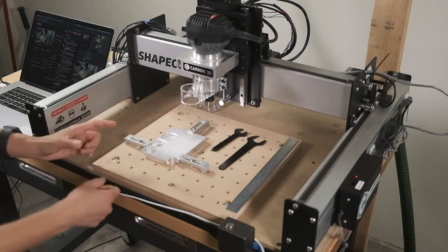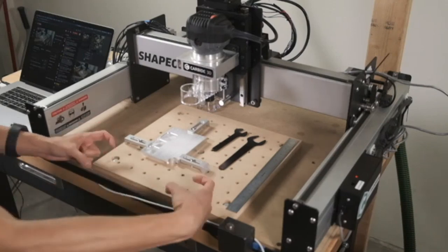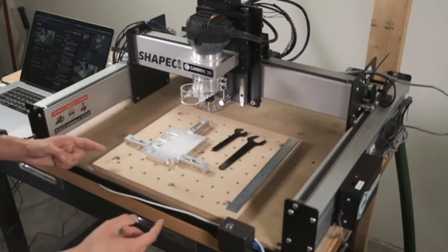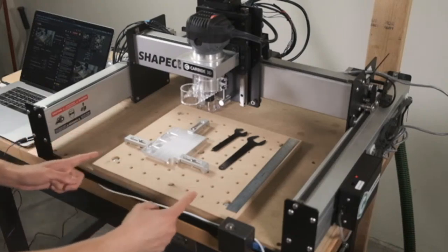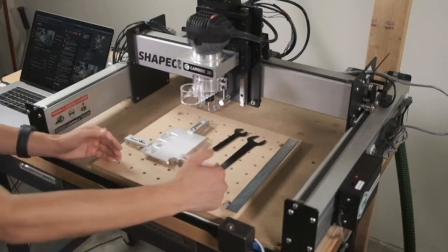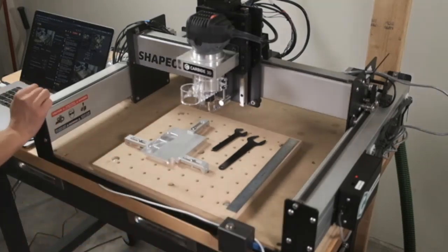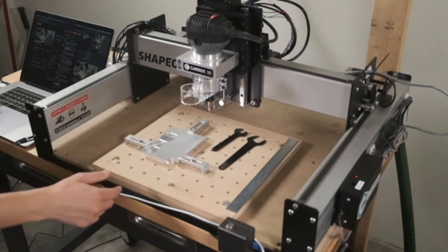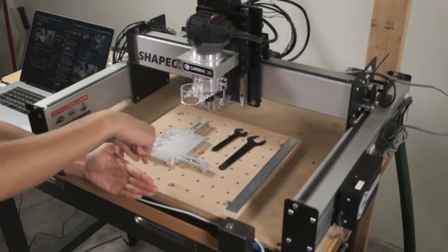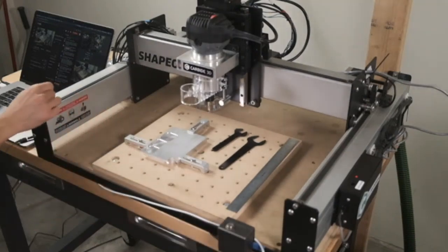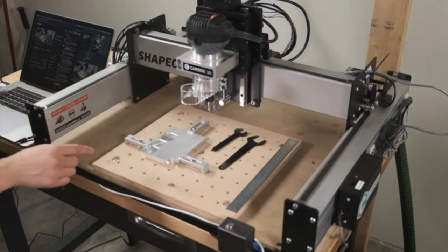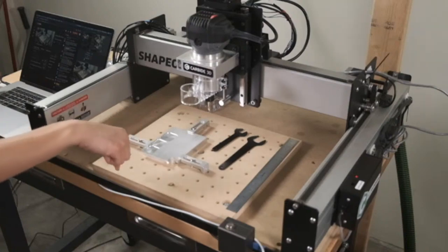Different ways you can clamp it. You can just take F clamps or something, or you could put some threaded inserts into a block here, or use a 1, 2, 3 block and then bolt or clamp to that. And then making toolpaths to cut dovetails, like to just slot through a board, that's up to you. You could do Carbide Create, Fusion. Basically, you just need a cutter to move in a line forward and backwards.